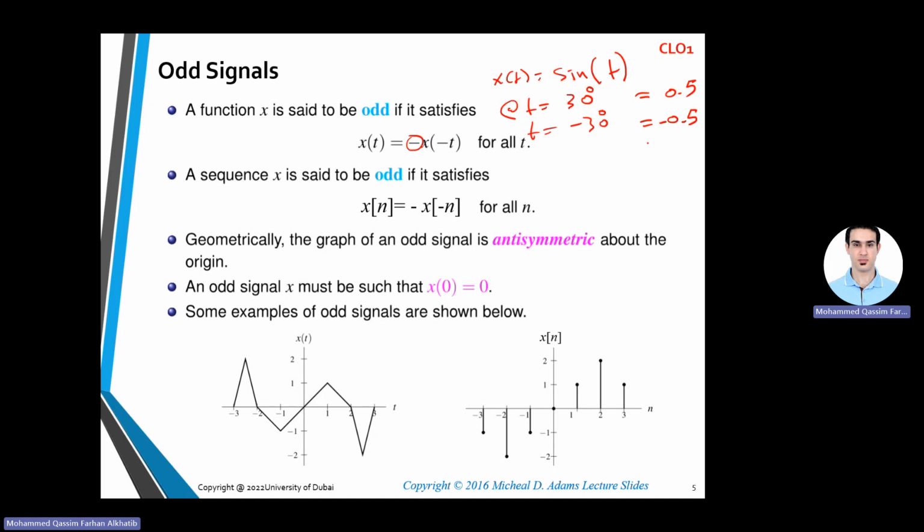It's not a trick, I will not call it a trick. It's something like doing it smart. Instead of wasting time to find the coefficients that end up being zero, from the look of the signal, if my signal is even, I know that the coefficients of the sine parts are all zeros, and I'm going to have only the coefficients for the cosine part.